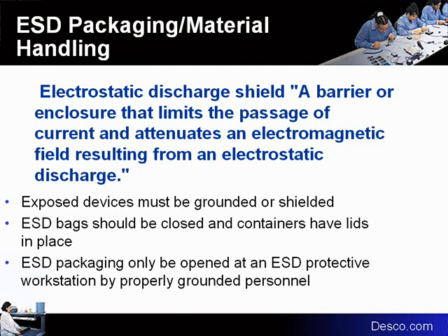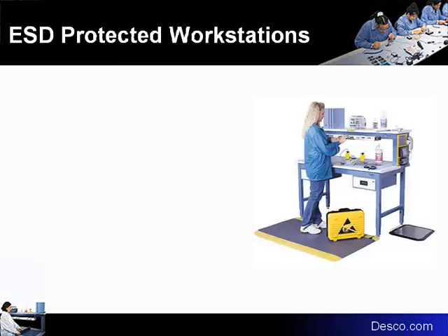The other dimension of shielding that is found is ESD garments, which have the same shielding effect for clothing. Clothing are insulators, and if they have a charge, it will not be reliably brought to ground via the wrist strap. So the ESD garment provides a shielding factor for the operator's clothing.